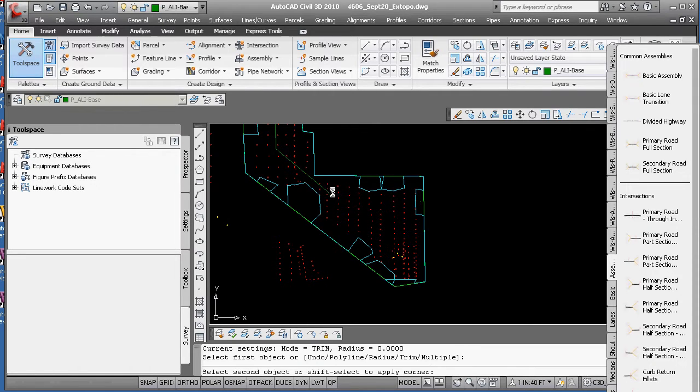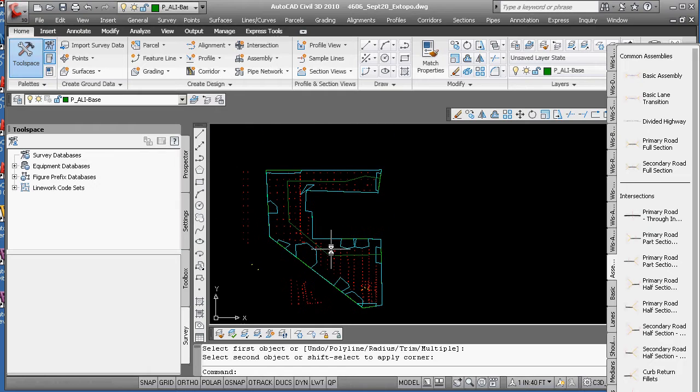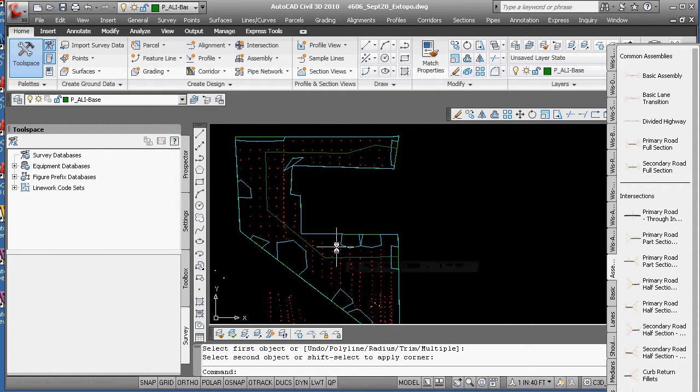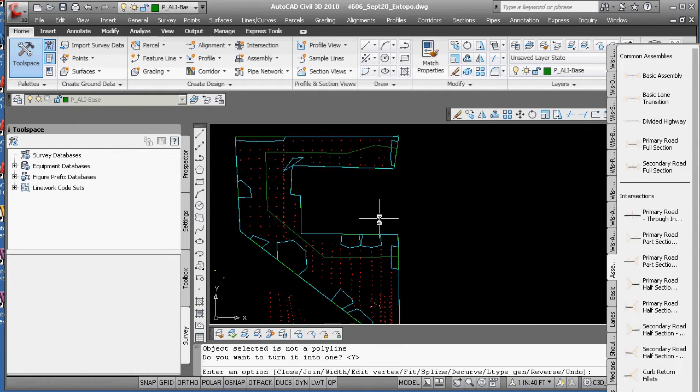With the concept, I would say start thinking of these as pipes. Don't do the curves that you've learned for now. You let the program fill that in. You want to get the concepts of PIs, points of intersection, so you can learn to write station equations and adjust your curves without going into a dizzy. So I'm now going to polyline edit. This is from last semester. Yes, join. There are going to be a lot of different ways to make alignments.